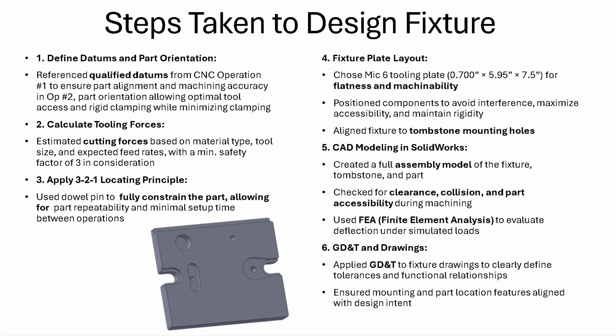Now the steps taken to design this fixture were: we defined the datums and part orientation, then we calculated tooling forces, then we applied 3-2-1 locating principles to fully constrain it, then we did fixture plate layout, then we did CAD modeling in SolidWorks, then we did the GD&T and drawings.